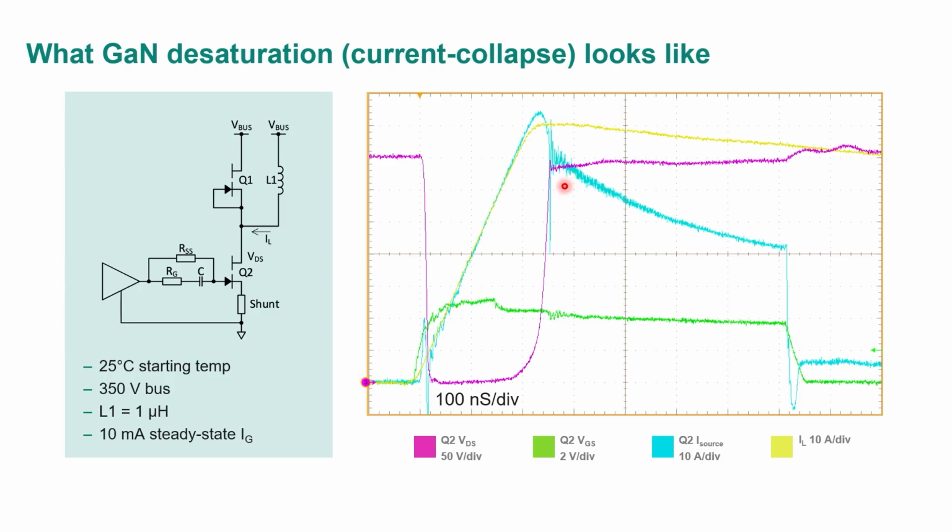This isn't going to last for too long before the device is destroyed. If I kept this on a little bit longer, it would completely fail. So this is almost like a short circuit test that I'm showing you here, but the key is that when you exceed the rated current limit, it's not just a linear thermal problem, where you're 10, 20% over and it's okay. It's not okay, because once you exceed that saturation threshold, the transistor opens back up. It doesn't support the current anymore.